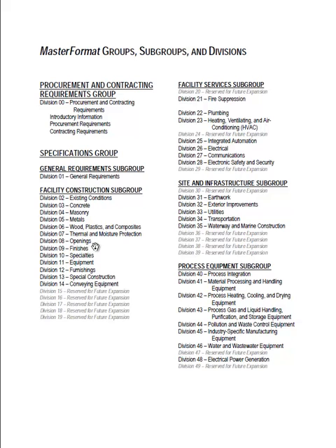Division 8 is openings. That includes doors and windows. Division 9 is finishes. This would be your paints and any type of exterior finish or interior finish would be included in Division 9. Division 10 is specialties. And this might include things like operable partitions, toilet partitions, rolling doors would be under openings, but any type of special equipment that's required would go under specialties.